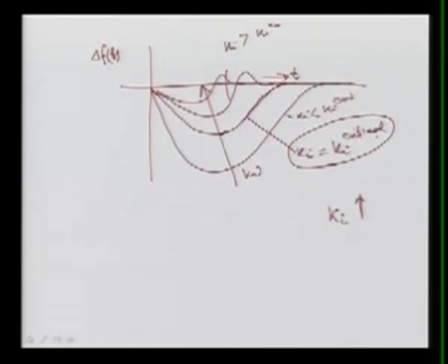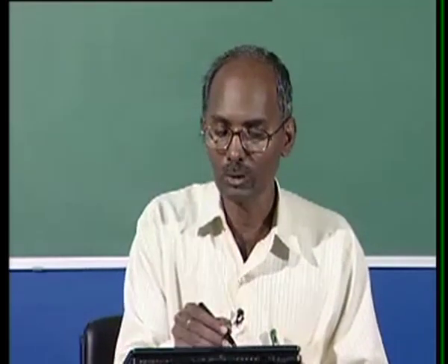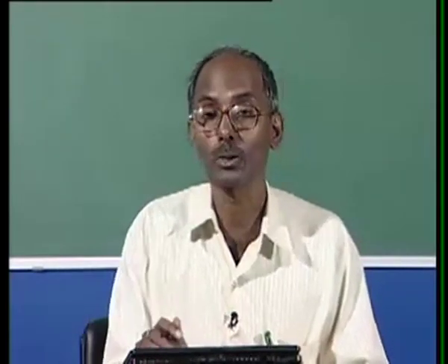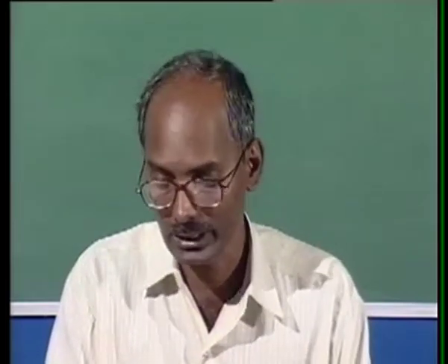You can see here we are getting zero steady state error, but we have to see by setting the value of Ki, which is very important, and it can be changed because it is a controller gain. Then your performance time is also changing. Here is the settling time. So we want to see how much overshoot and how quickly it is settling. So Ki is a very important parameter, decided once we calculate the critical value, and then whether we increase or decrease it, you can achieve the performance accordingly.